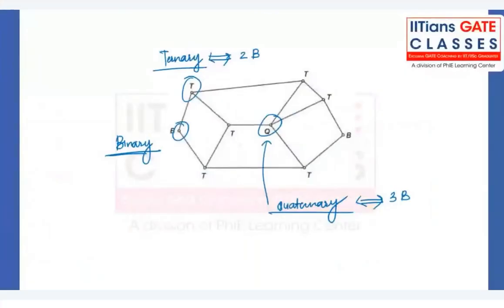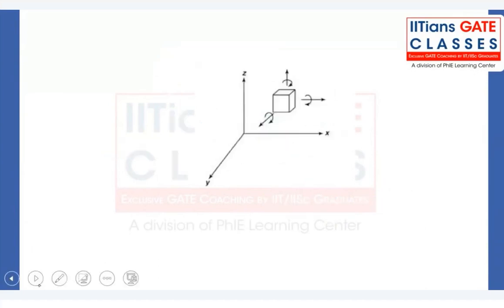So making the joints is not the only purpose. Here we should have constrained motion between the links. That is also equally important. So we should understand the concept of degrees of freedom. The degree of freedom of a pair, we can say, is the number of independent relative motions a pair can have. It can be either translatory motion or rotatory motion.